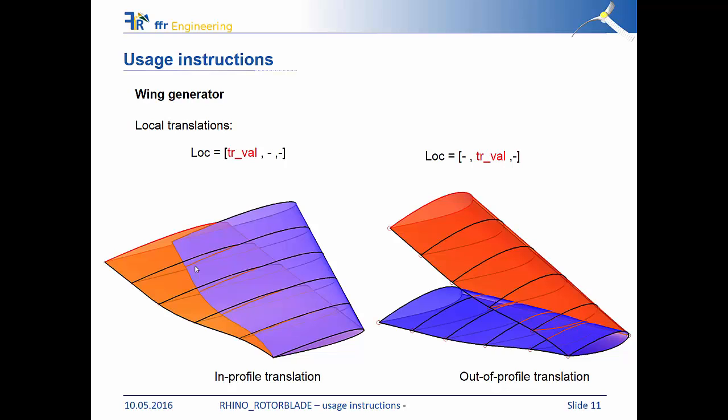Now you might ask, this process could be automated. Yeah, you're right. Of course, if you know the wing length and if you know how many profiles you want to add, then you have here the position, the X position along the longitudinal direction. Nevertheless, at the moment this is not done for you, so you still have to simply add that. That's very simple. You can have a look at the sample codes provided with the software. And we do that because some people might want to play around a bit here. So maybe at the beginning, where you have a bigger change of the geometry, you might want to have a closer network of added cross sections, and maybe in the back you want to have more space between the cross sections. This is why we give you the flexibility.